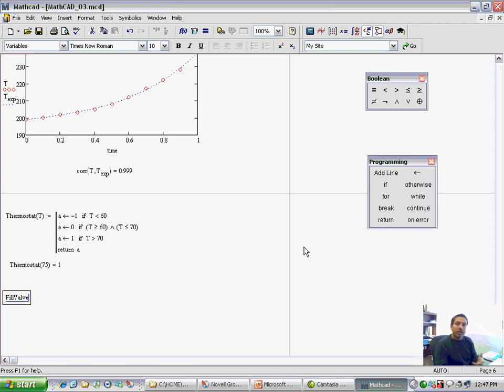It's just a function that takes on a couple values, like this thermostat takes only -1, 0, and 1. The field valve is only going to take, in this case, open or close. Okay, so not only is this one a discrete type of function, it doesn't even return numerical values, it returns strings. So the field valve depends on a level. Depending on the level of a tank, this valve is going to send a signal to the pump, or to the gate, to the solenoid valve, to either open it or close it.